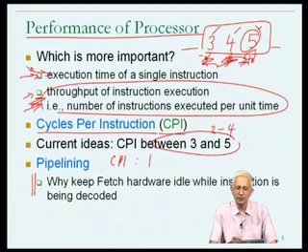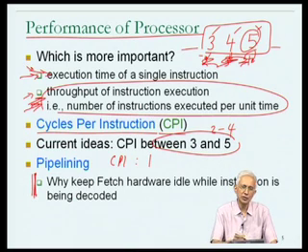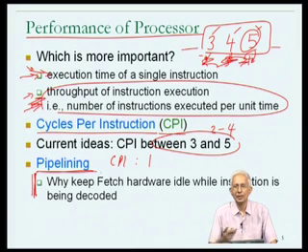We never asked the question listed over here. The question is, after the piece of hardware which was meant to fetch the instructions from memory had fetched the current instruction, why do I keep it idle when that particular instruction is being decoded? Why can't I use that fetch hardware for something else? This is the fundamental question which provides the idea of pipelining.